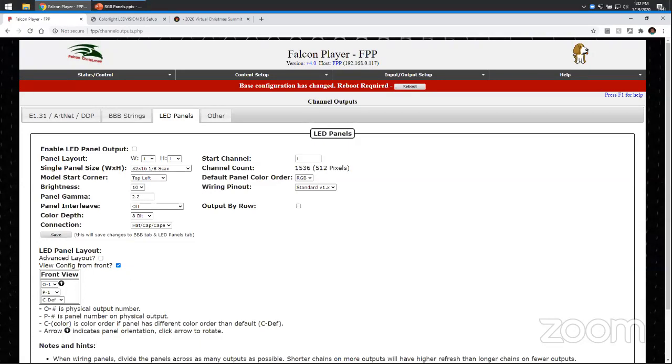The wireless cards built into single board computers are typically not great because the antenna is too small and it's stuck inside a whole bunch of metal and electromagnetic interference, so you usually don't get very much range off of them. If I was going to go wireless, I would add a wireless card so I could get some range out of it.